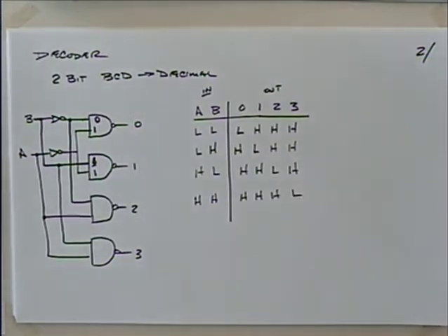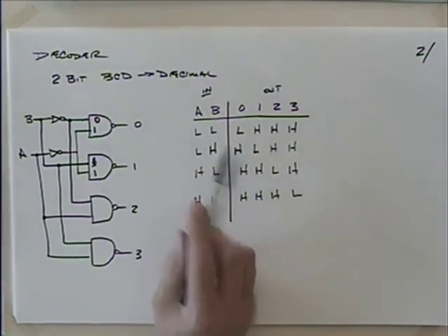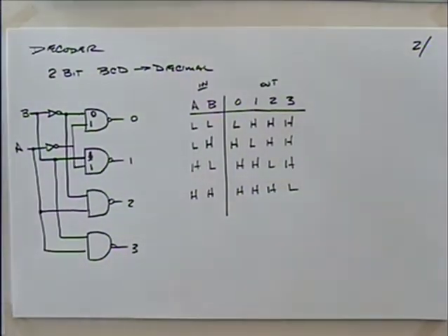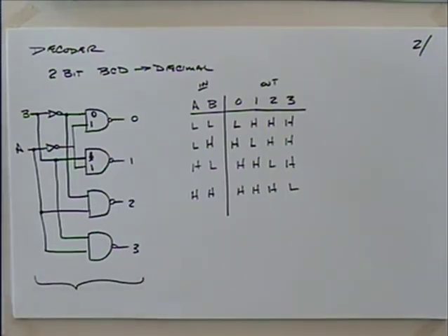So you've really got a 2-bit binary number A and B going to a decimal output. And you could do a 4-bit. You're just going to have a lot more gates there. So this is actually one of the things that you're going to be building this week in laboratory. One thing that's probably a little confusing here is that it's activating on the low, and sometimes they do that depending on whether you want to turn something on or off or how your logic is arranged. Questions with that? And I think on the website it has a circuit diagram for this to help you with Lab 7.